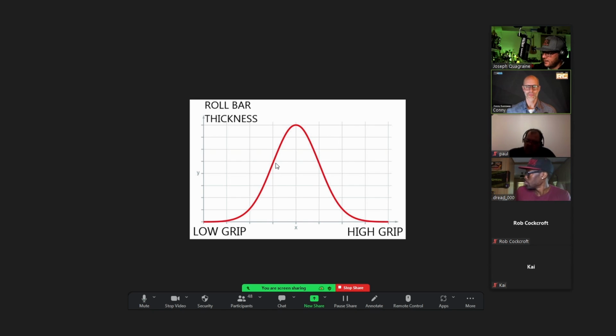Let's say you have a small roller, and in that section you hit it just a bit wrong and the tire catches, the front tire lands and catches afterward. With a thick roll bar, the car would just suddenly flip over. You don't want that. You want it to be a bit more forgiving so you have time to respond to these kind of things, right? So going to a thinner bar would allow the car to absorb those kind of situations.